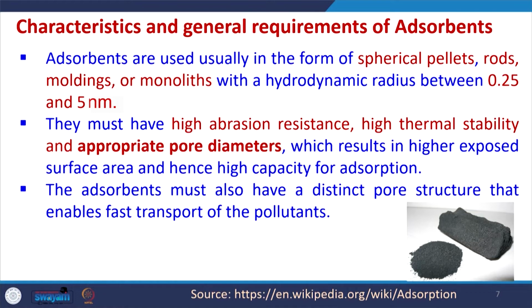So, we always try to select those adsorbents which, when used in the packed bed, should have a lesser pressure drop when the liquid or gaseous stream is moving through that bed. So, that is a very important consideration in selection of any adsorbent. This is one of the features that we always take care of, or we select the adsorbent in such a manner that the pressure drop criteria is met.